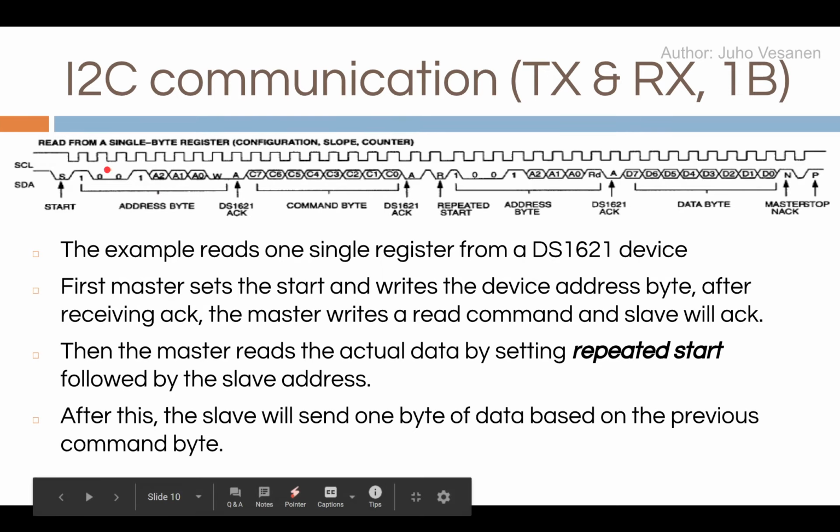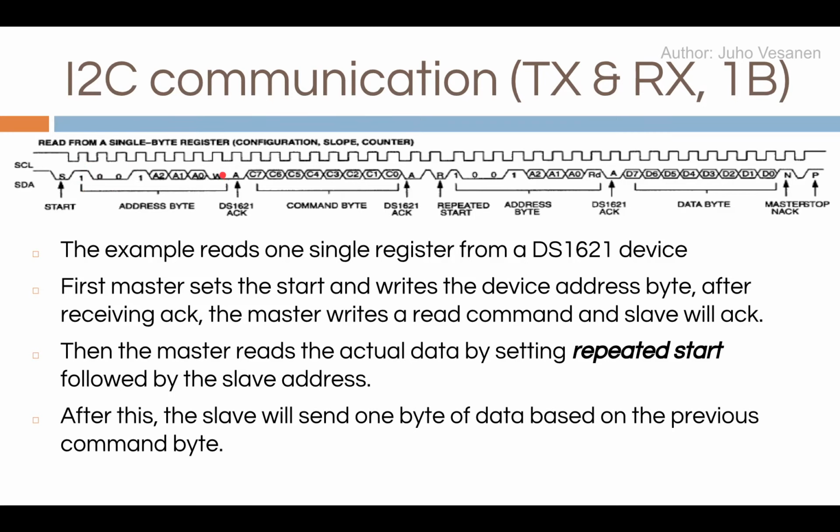So first the start sequence, then address and write, waiting for the acknowledgement, setting the command byte, and getting the acknowledgement. Here comes the repeated start.